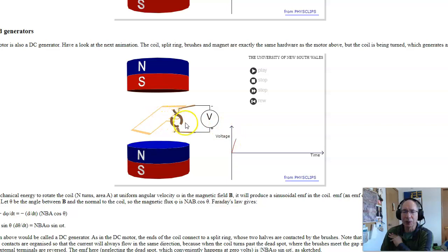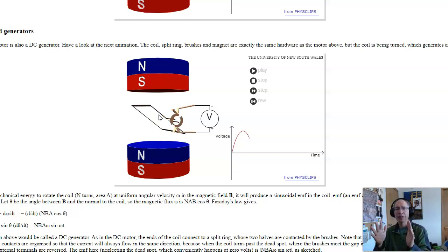In addition, when I switch out a lead, I have energy in that magnetic field. That energy has to go somewhere. And what happens is as the field collapses, the current goes to zero. The energy, well, it creates a current spike. The energy collapses, producing a spark.